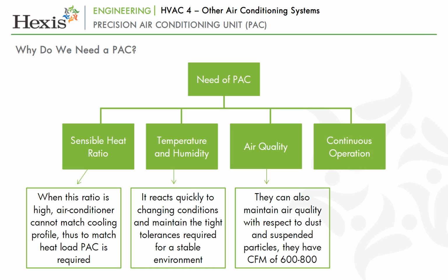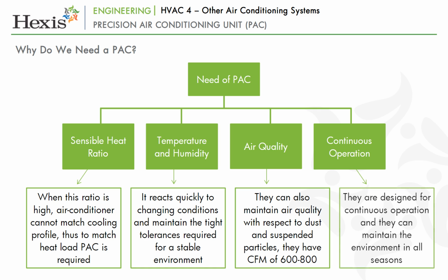Continuous operation. The equipment in rooms critical to business runs almost through the year, and so is the expectation from the supporting infrastructure. PACs are designed for continuous operation, maintain the environment in all seasons, and redundancy is normally built in the design to ensure continuous availability of required functionality.